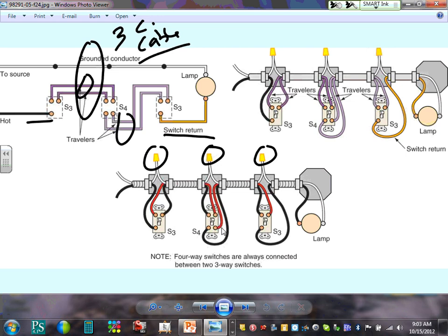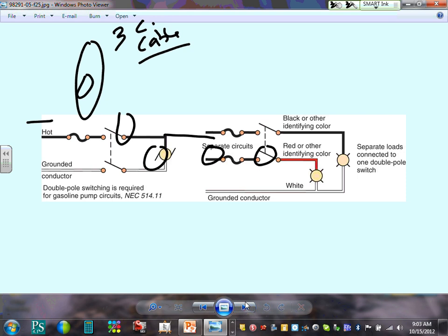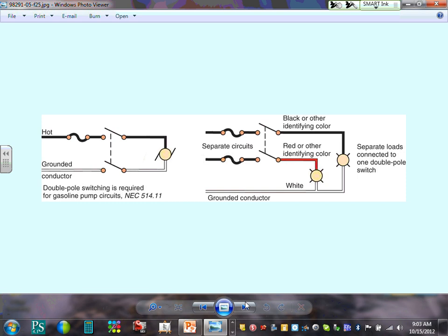Any questions, guys, about three- and four-way switches? I assume by this time everybody's okay. Okay, this is two-pole switches. You use them in a two-circuit system. Suppose that I have, I don't know, these switches. You will switch two circuits. This circuit is 208. Suppose you have a 208 voltage. You brought a circuit to multiple lights, and then to switch the two circuits together, you need a two-pole.